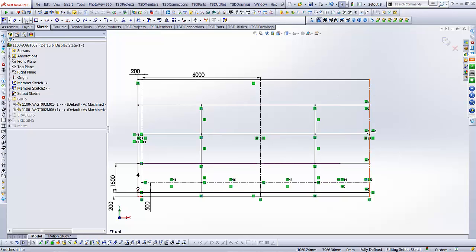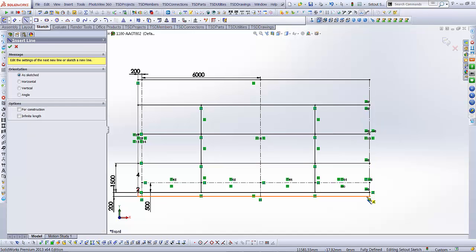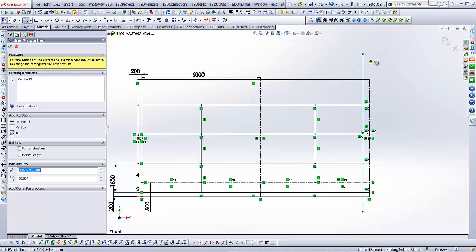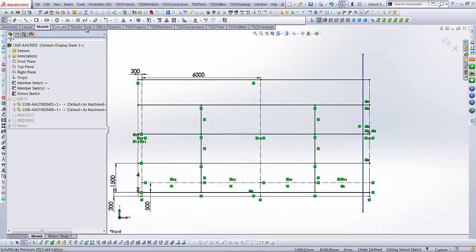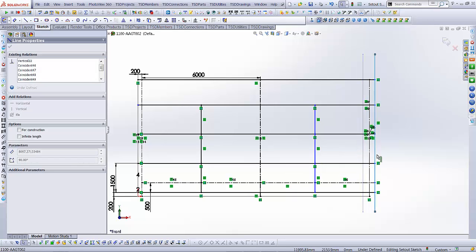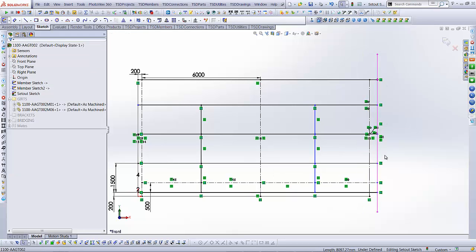You get that when you're modeling. Some things always change when you're going through the process of the design intent. So I'm just going to draw a line here and do a trim on all those lines, and trim component is under the sketch, so we just grab that, and you can do a power trim that just snaps all the lines. Okay, now I can bring that out to there.